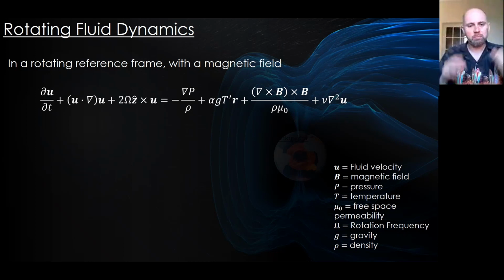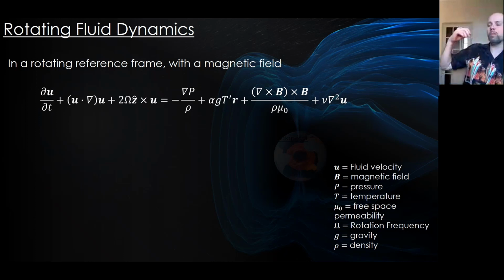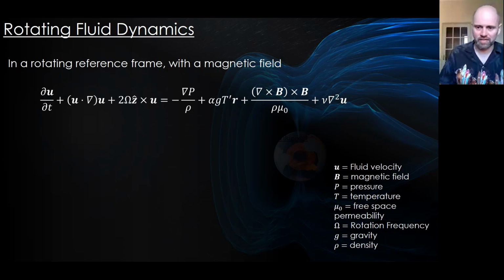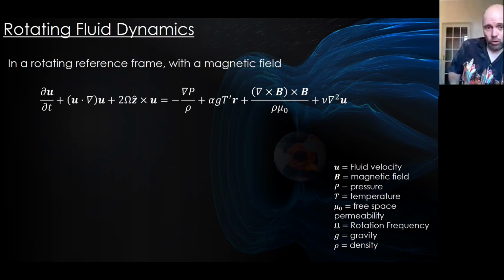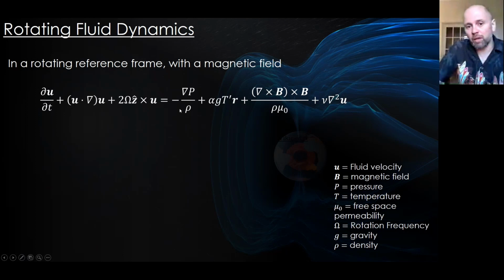What I wanted to do is point out some facets of the Navier-Stokes equation that are particularly interesting in the geophysical context. All your variables are down on the right-hand side, and hopefully there are a few terms that you already recognise. The Navier-Stokes equation is really a statement of Newton's second law of motion, applied to a moving parcel of fluid. The acceleration terms are all on the left-hand side, and the first two are the material derivative, where you're following the motion of the parcel. And then you've got the sum of all the applied forces.